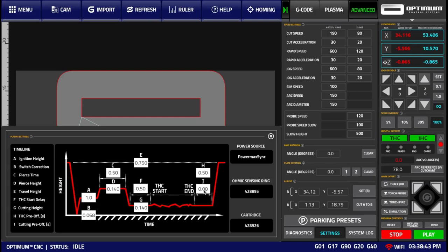For instance, if you are cutting a piece of metal and you have a metal part that will be dropping after you finish the cut, perhaps you don't want to actually finish or finalize that cut. Perhaps you want to leave just a tiny little bit of metal so you can remove that part by hand, etc. So this is typically kept at 0.